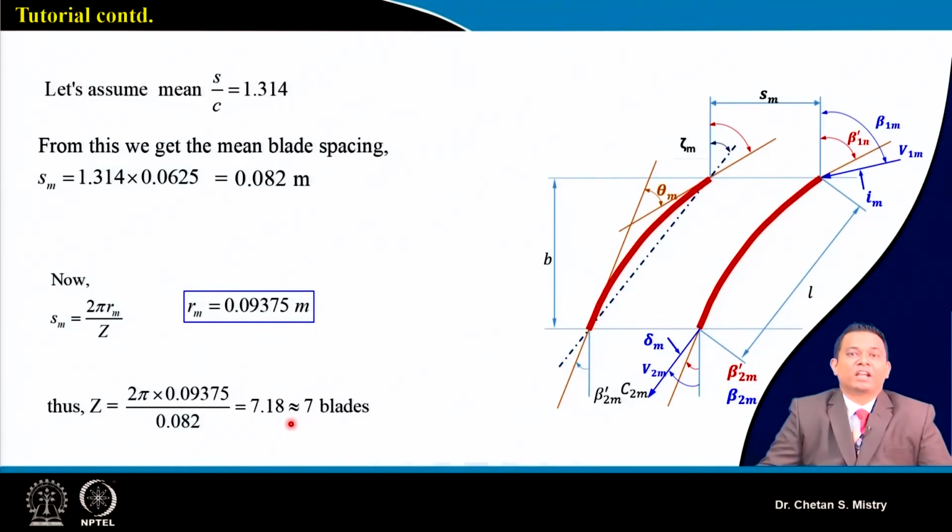Okay, so you can understand this is what we need to keep in mind. Here you can assume number of blades to be 5. You can do your calculation for your pitch, and accordingly you can go ahead. That is also one of the possibilities. No one will stop you, but when you are taking these numbers, you need to have proper justification. It is not like I will take one blade. That is next to impossible. Just realize that part. So understand this is what we are looking for in terms of doing the design. So now we have the number of blades to be 7.